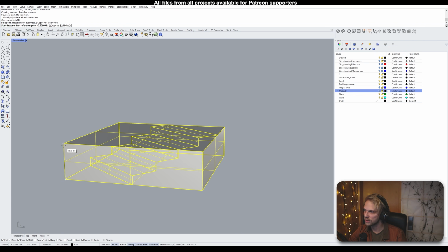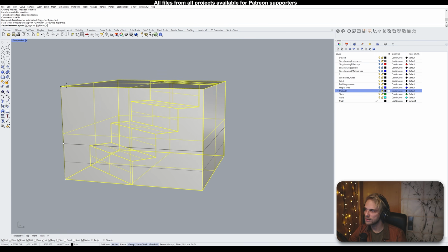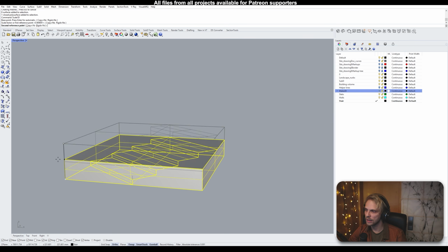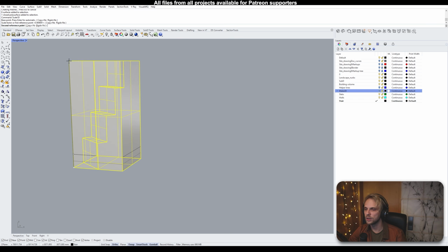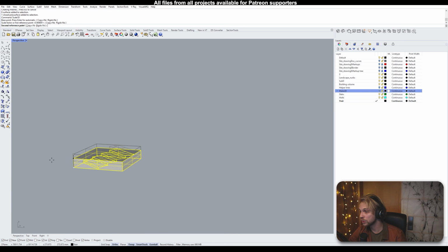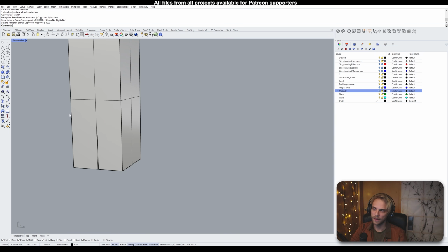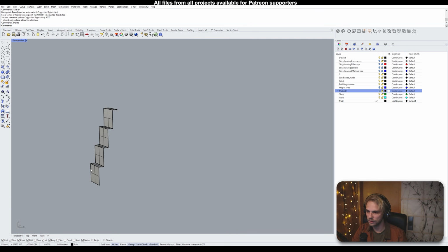So along its height, you can scale it to whatever height you want, right? So let's say you want to cover 4 meters in height with 4 steps. You can, if you want to. You just type in 4,000. And that is how your staircase would look.